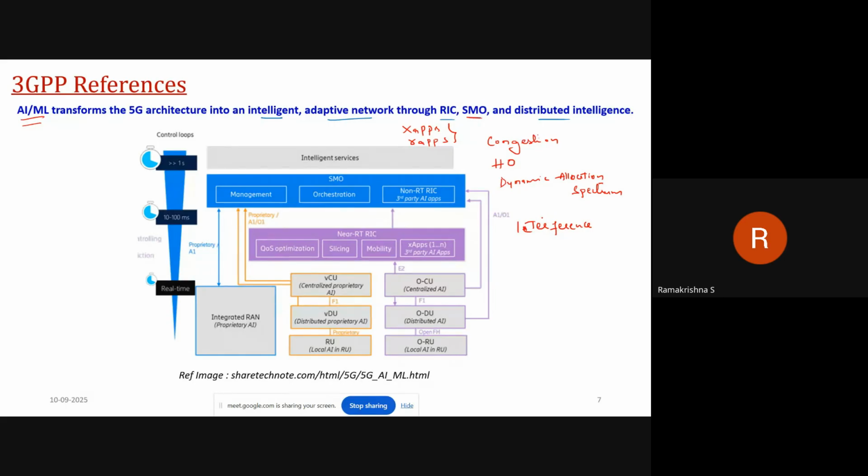Think of one scenario wherein the system predicts heavy traffic at a junction. It can pre-allocate more radio resources to that particular area, ensuring that vehicles do not experience any delay in safety-critical message exchange. I just mentioned two such messages; there are 13 different IEEE standard messages exchanged between two vehicles, and BSM and CAM are examples I mentioned. This transforms the entire V2X communication model into a predictive, adaptive system.